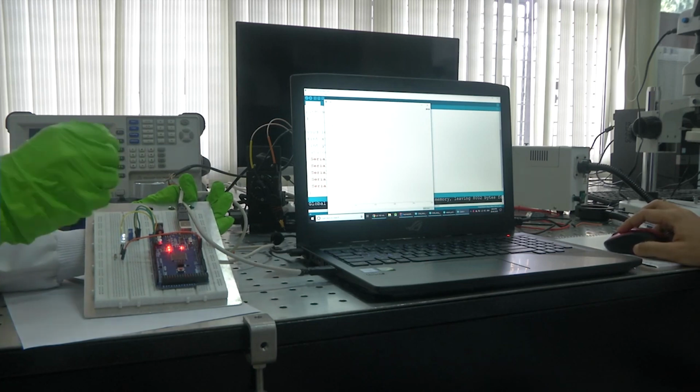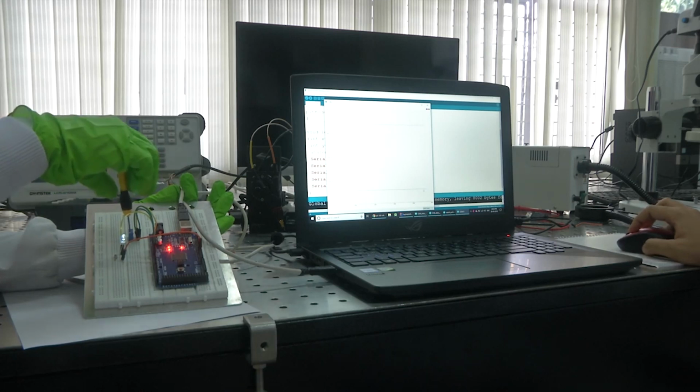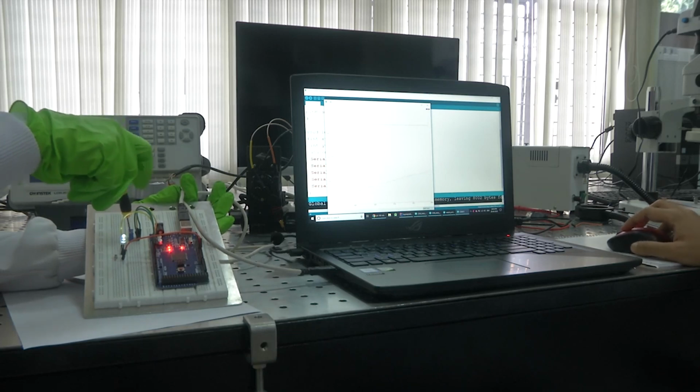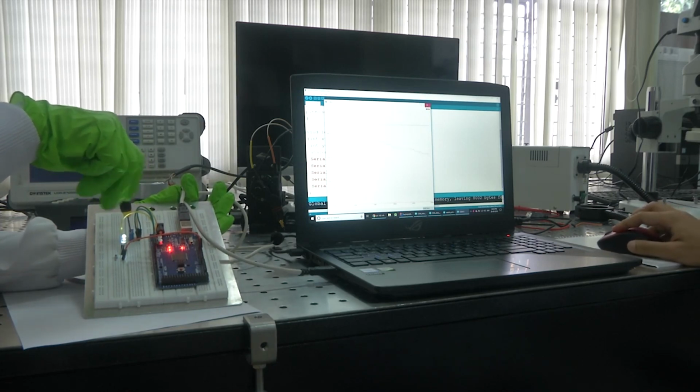See, this is the 1023 line and this is the 0 line. Now when I change the value of the potentiometer, you can see it actually increasing. So it's not scaling. This is not a very recommended method, but I am showing this because the scale won't change now here. If I turn in the anti-clockwise direction, it's going to reduce. This is how we take analog input and print it in a serial monitor.